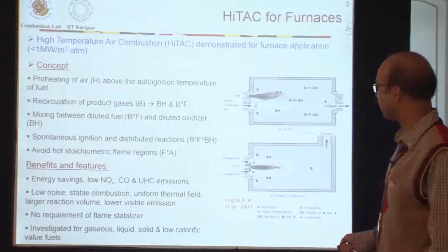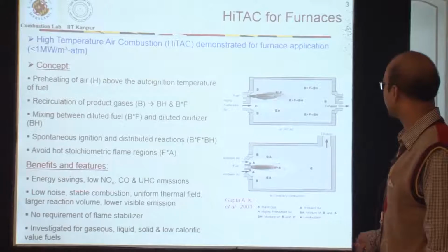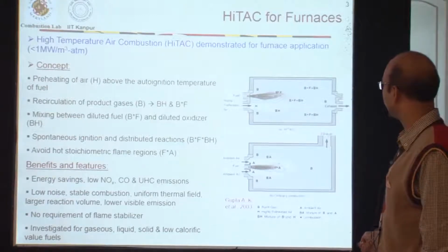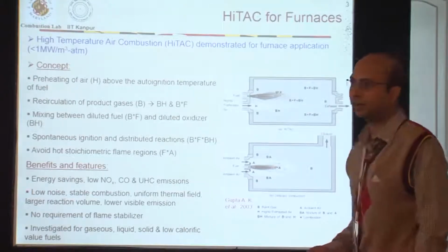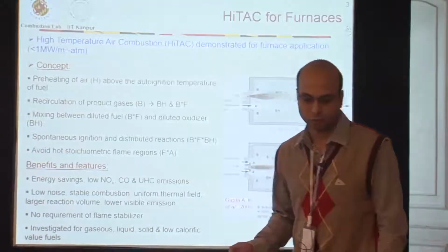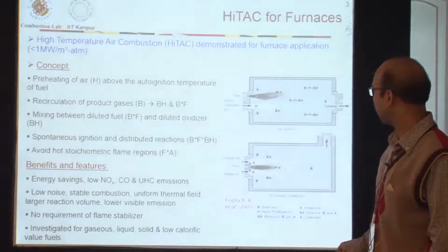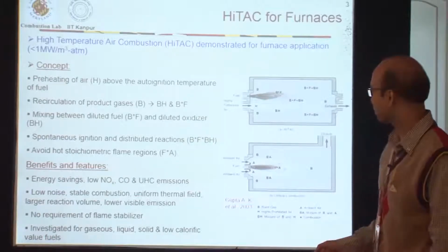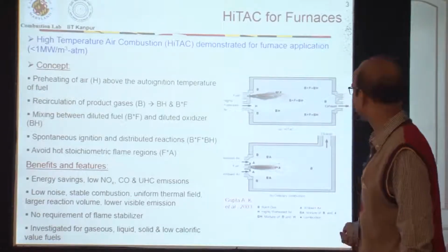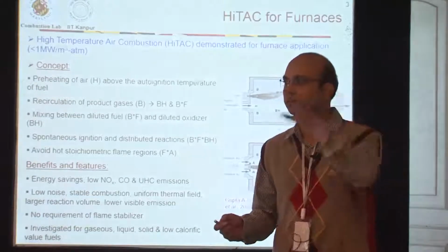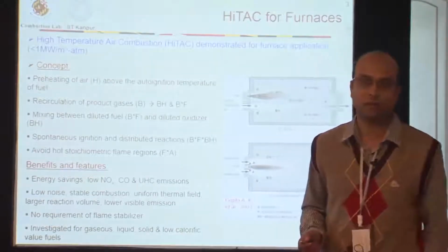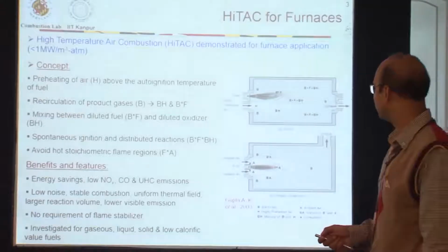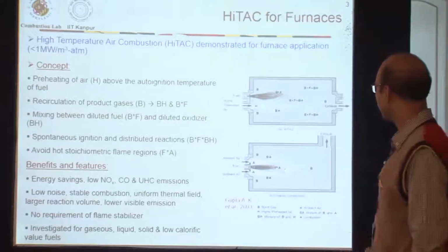So that's how you achieve more uniformly distributed reactions. And benefits: because you are extracting energy from the exhaust, you definitely get energy savings, and other important benefits are very low pollutant emissions, a very uniform thermal field, large reaction volume, and in this case you don't require any flame stabilizer. You are directly injecting fuel and air inside the volume, so you don't have any swirler or any bluff body, so to say.